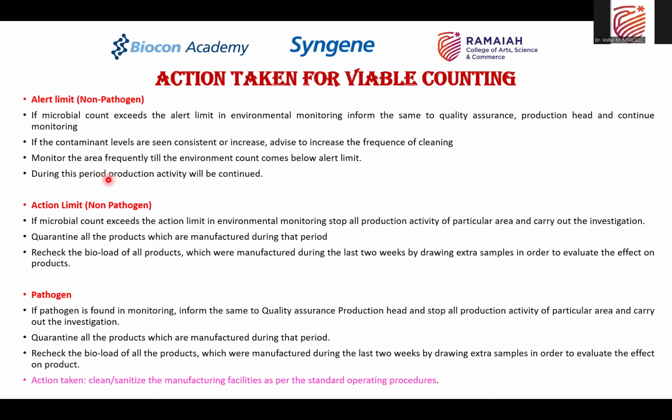So what will be happening? The production can continue if the microbial count is consistent in the same range. You can continue the production, but some alert or information is sent to the quality assurance and production heads, and the frequency of cleaning is increased. So we are going to monitor for the presence of microorganisms, and the cleaning frequency has to be increased so that the number of microorganisms will not increase.